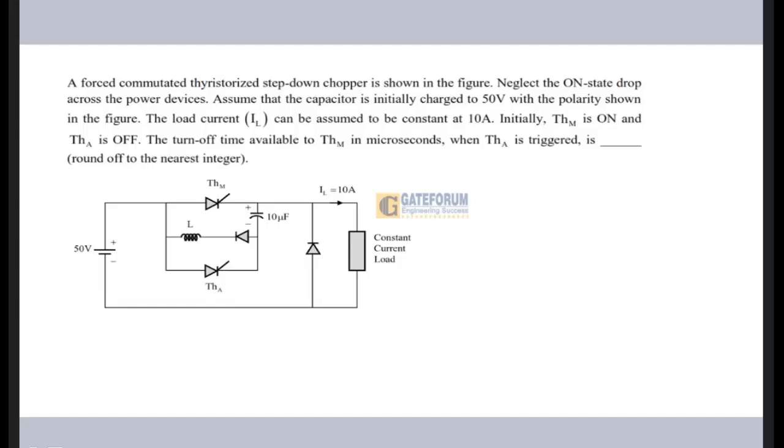So here, this is the value of the output current or the load current, which is constant. And why is it constant? Because of this freewheeling diode and because of the continuous conduction. They have asked the continuous conduction case, and we have discussed the class B and class D chopper by assuming continuous conduction only.